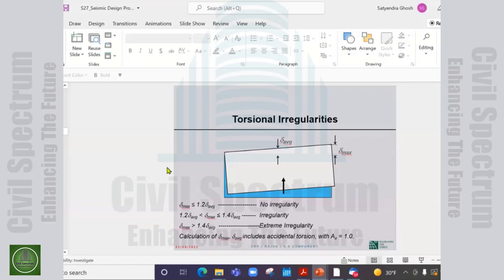From the definition of soft story and weak story, we know what they are, but you didn't tell us how to evaluate them. Dr. Ghosh went over it. What do you mean by evaluate? I specifically said strength is the shear carried by the lateral force resisting element, and stiffness is the reciprocal of deflection.